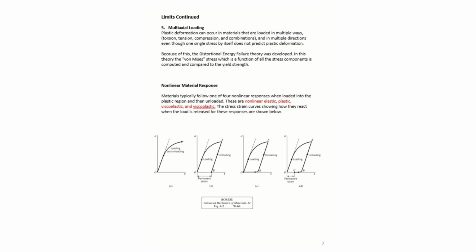And so when we do account for all those different types of stresses, what we usually end up computing is what we call the von Mises stress. This is also called sigma prime. In some finite element codes, it's called the equivalent stress, such as ANSYS.